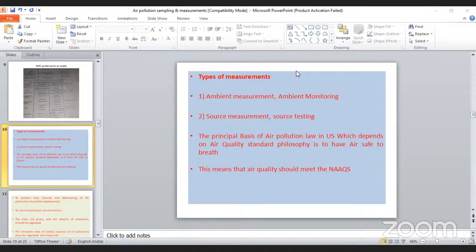It is a very simple method to be adopted, and we will come to know the concentration of particulate matter. The thing is, in gravimetric analysis, quantitative chemical analysis is done by weighing the sample, usually a separated and dried precipitate.